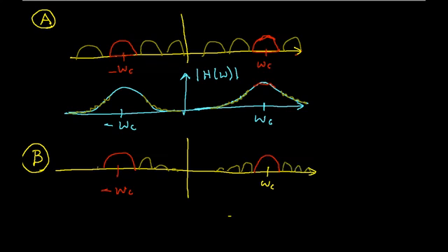Now, because my bandpass filter does not have a sharp cutoff at the edges of the passband, these guys are still pretty significant. They're not gone, and they're the junk we don't want to listen to. They'll get cleaned up later. At the output of my RF amplifier, I have something that looks like this magnitude spectrum labeled B.